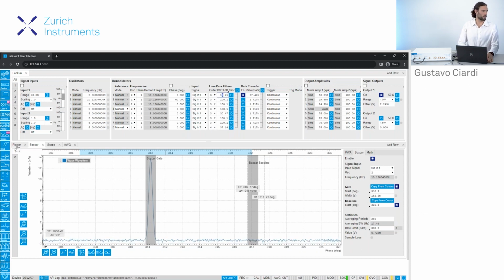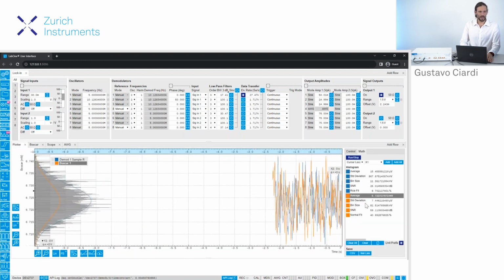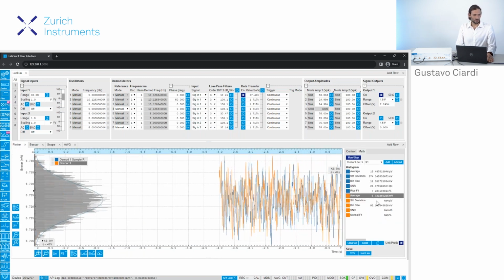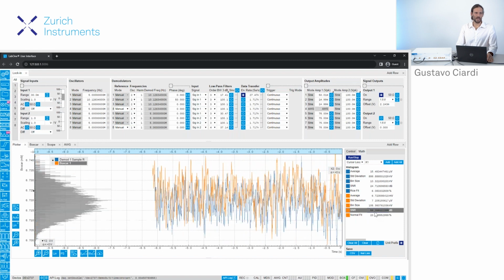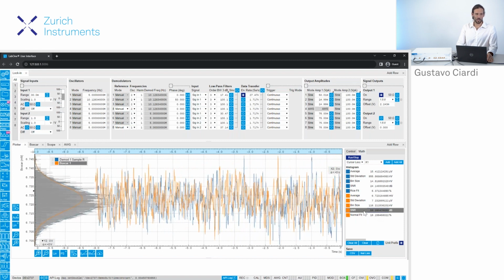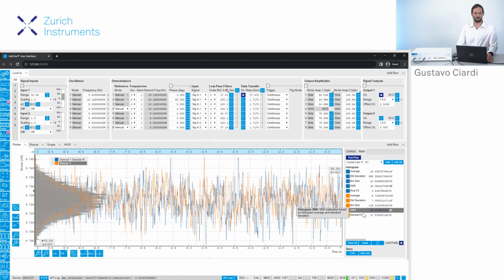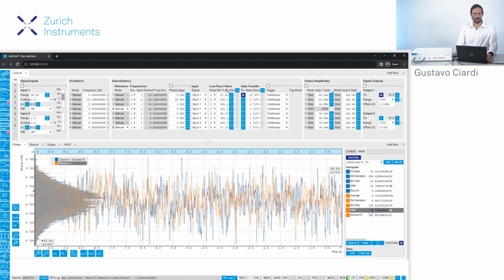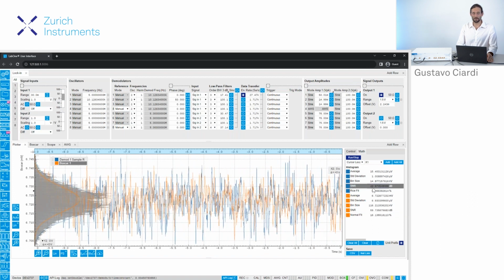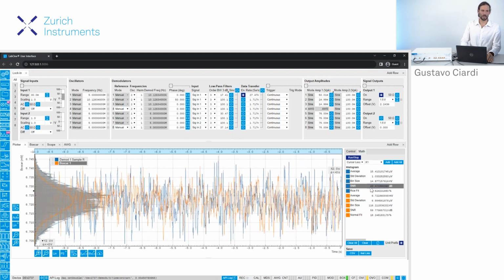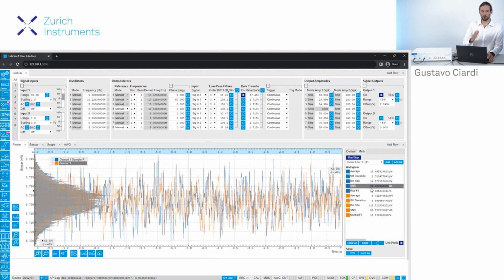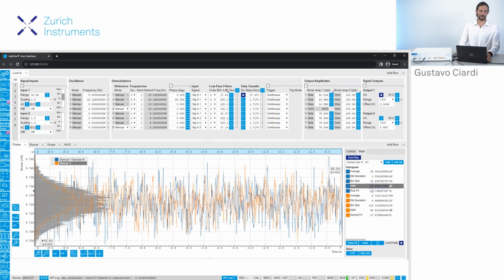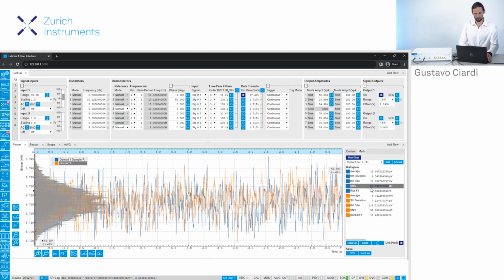If we now have a look at the plotter, we can clearly see that for the Boxcar averager the signal-to-noise ratio is much higher, 59 dB against the 23 dB of the lock-in measurement. So almost 40 dB different. This is almost a factor of 100.